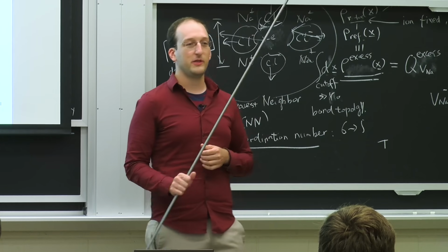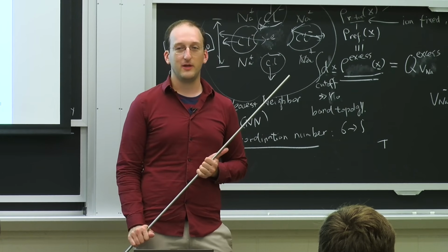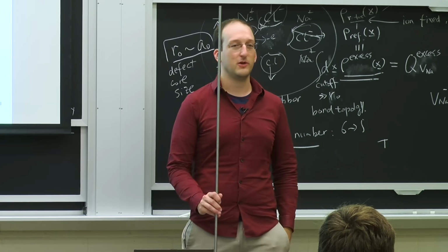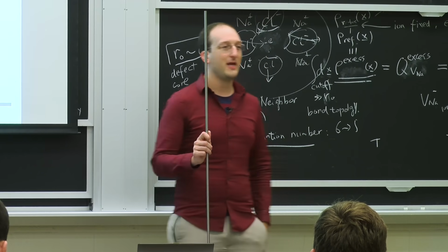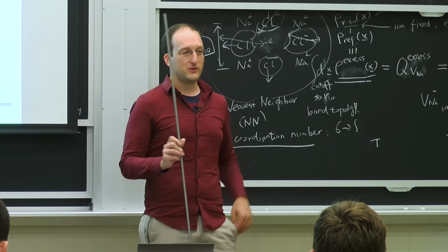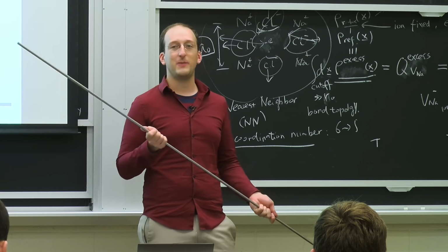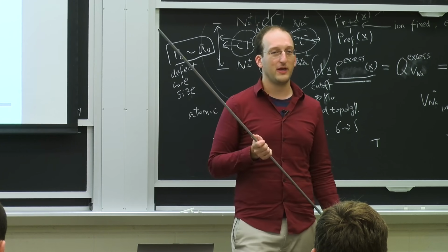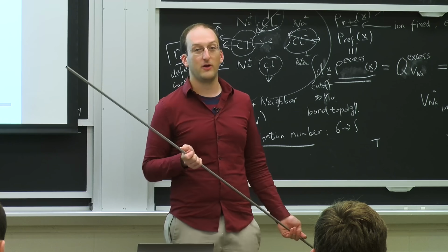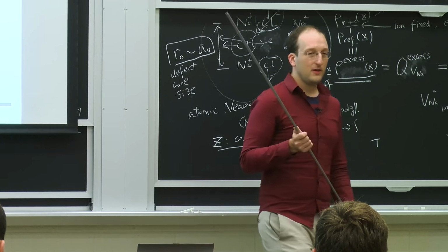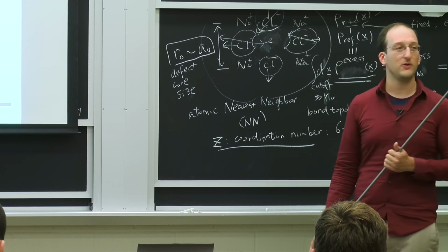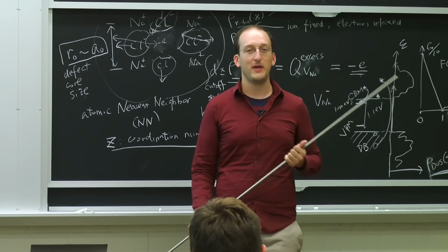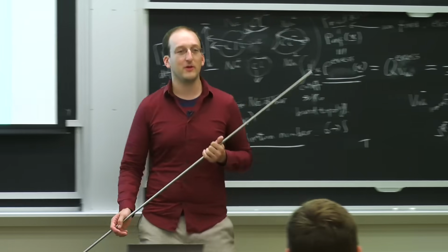Also, what makes this nuclear-grade Zircaloy and not just regular zirconium is that there's no hafnium in it. Hafnium is chemically very similar to zirconium. It also happens to be one of the highest cross-section elements that there is. So the stuff that you need to be neutronically transparent in reactors happens to be found in the ground with the last thing you'd want in your fuel cladding. In fact, you can use hafnium as a control rod or control blade. So the difference in chemistry and in cost between nuclear zirconium, what you've got there, and regular zirconium is that the hafnium has been taken out by some very painful chemical separation. Usually you'd find about 3 or 4% hafnium.